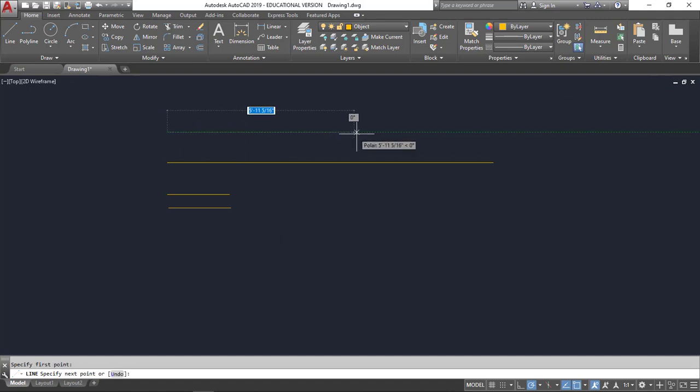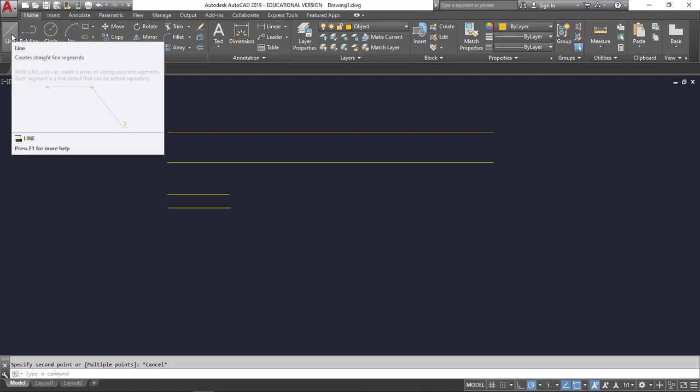I can also type in 10 feet 6, but I don't need to put the 2 ticks at the end because again, it automatically defaults to inches for my last value. So let's check that. Distance, 10 foot 6. So let's say that I want to put a fraction in my length. So we'll use 10 foot 6 and 3/8 inches.